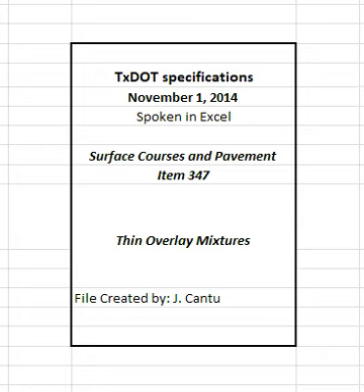4.4.2.2.2 Conditional approval of JMF1 and authorizing trial batch. The engineer will review and verify conformance of the following information within 2 working days of receipt. The contractor's mix design report, JMF1. The department-provided overlay test results. The contractor-provided Hamburg wheel test results. All required materials, including aggregates, asphalt, and additives, and the mixture specifications.